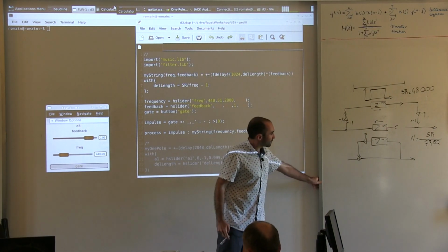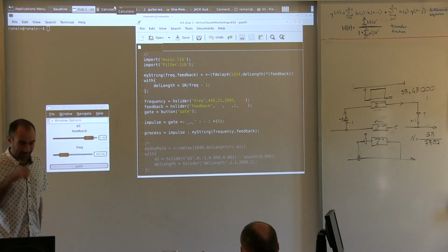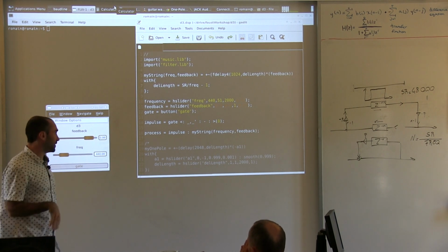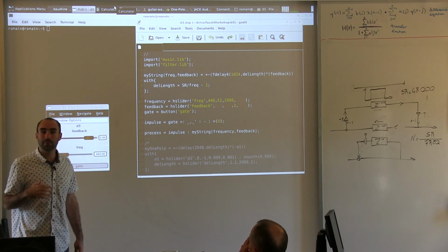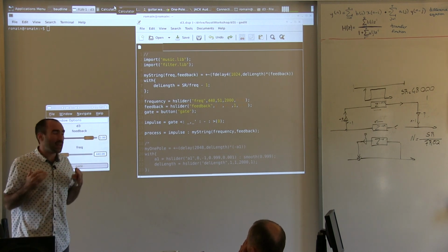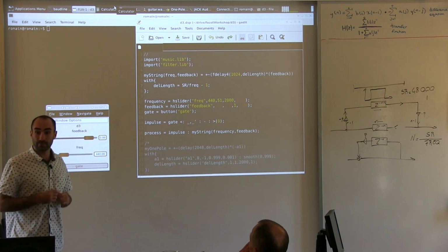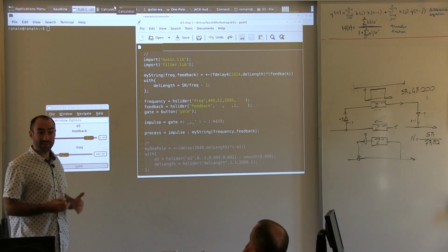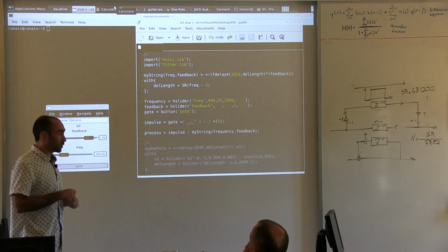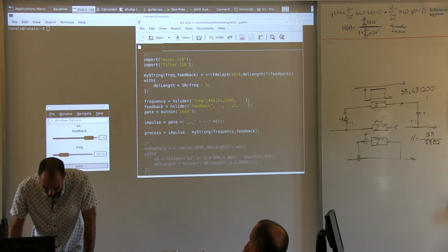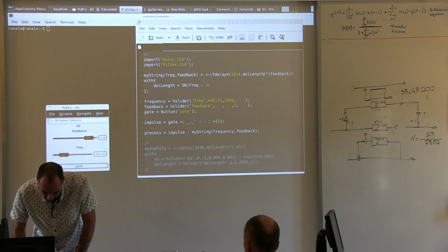So, in the traditional Karplus-Strong algorithm, or if you read the Karplus-Strong paper from the 70s, the way they did that is in a very, very basic way. You can make that in a very complicated way. You can design extremely fancy filters to do that so that it's going to sound really realistic. But the way they did it in the 70s was basically by just having a very simple 1-0 filter, a feed-forward filter that we also call a moving average filter, as Luc said this morning. So that's what we're going to do here. What we're going to do is, at this point here in the feedback, we're going to add a new step.